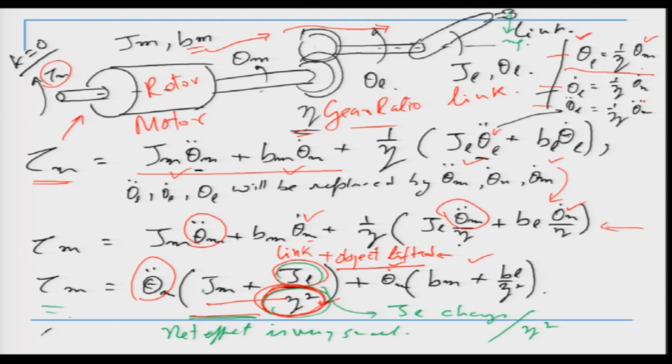is not reflected onto the motor, and that is the reason why once a PD controller is tuned for a particular mass, the mass is normally tau L, that same tuning actually works even when the robot picks up an object, because the object weight is not felt by the controller.